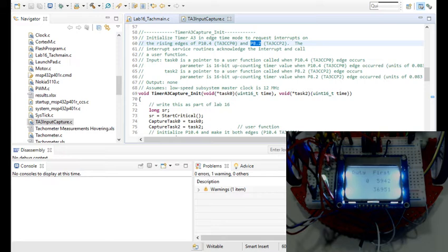But what you're set up to do is to set up a couple of tasks, and then you set up timer 3 to do a collect or capture when there's an event that occurs as these motors run. So as the motor turns, it's going to trigger an event from the motor controller through the controller board and on up to the MSP432, and they're using port 10 pin 4 and port 8 pin 2 for each one of the motor controllers for each one of the motors.